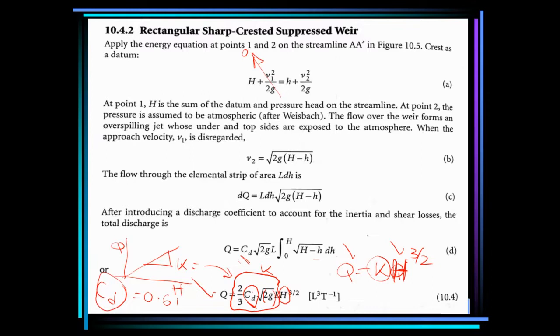Okay, it is dimensionless. So what is the significance of this value? This is about 61%, isn't it? This is about 61%, and that means that the actual discharge is just 61% of the theoretical discharge, because CD is QA over QT. So QA, the actual discharge, is CD times QT.